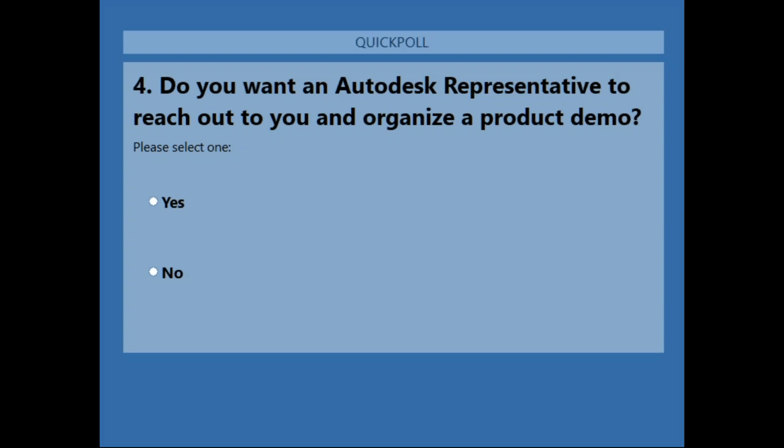In order to get a good registration in ReCap, how many scans should be taken? It all depends. Earlier I talked about a basement facility where the scanner took scans in 8 different locations, the range of that scanner was quite good, and it took almost 80 minutes to process. So depending upon your equipment and the quality of scan you want, there are no such thumb rules, but the more scans you have, the heavier the model might become in certain aspects.